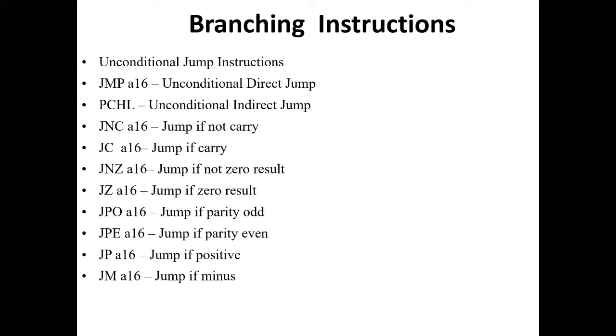Next is JZ A16. JZ is a mnemonic which stands for jump if zero result. This instruction is used to jump to the address A16 provided in the instruction only if result is 0, indicated by zero flag value of 1. If zero flag value is 0, program flow continues sequentially.